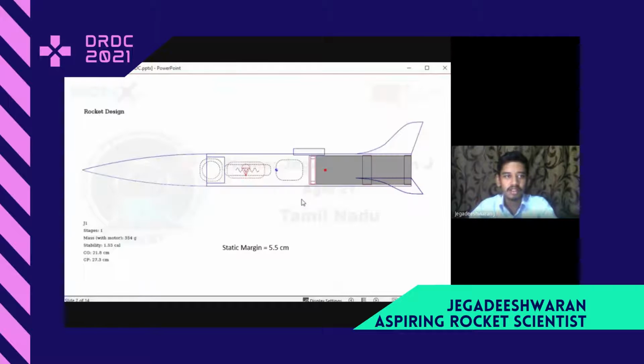This is the final design of the rocket. The nose was designed to have minimum drag while having continuity with the body tube. The body tube length was kept accordingly to have apogee at high altitude and at the same time have enough strength and space to hold and carry other components.